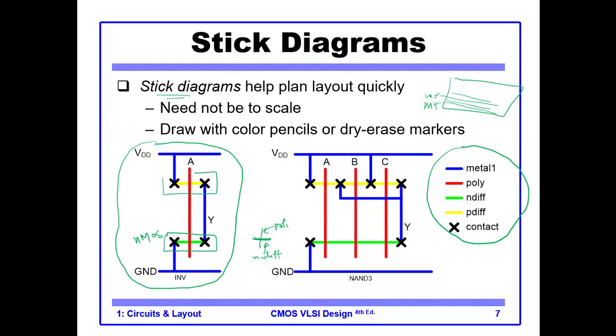So here you see this is a PMOS, okay, and the poly lines are connected and labeled A. So this is our source connected to VCC, our drain connected to the drain of NMOS. Okay, so this is our output Y. So what is this? This is basically an inverter, a CMOS inverter.